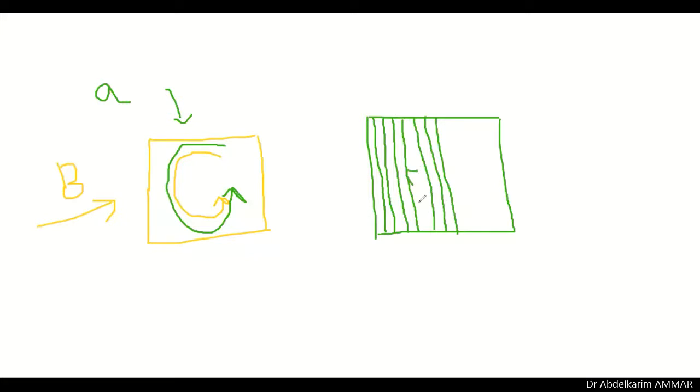Okay, so let's choose another color. This is the eddy current if we have small sheets. So in this case, we can reduce those currents because those sheets are isolated from each other with material. So in order to reduce the eddy currents, the magnetic core must be composed of compacted sheets.